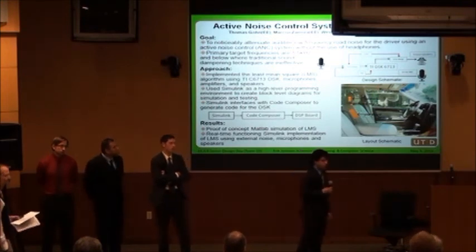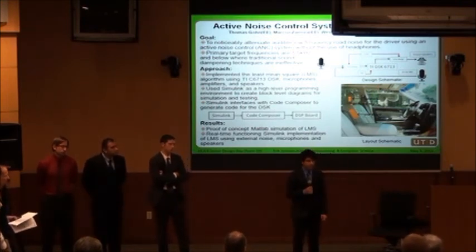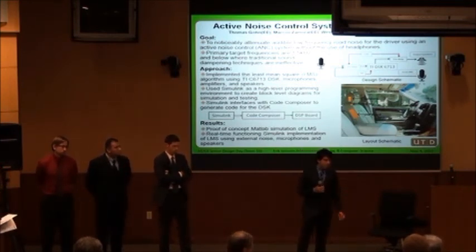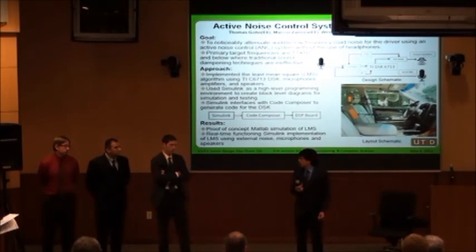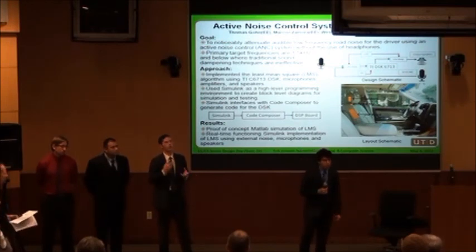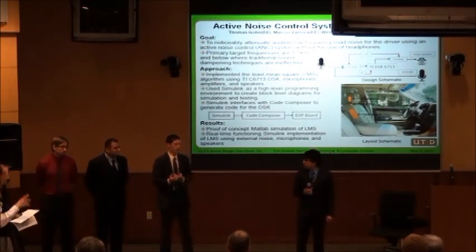One other thing, in your block diagram, you're showing both 12 volt and 5 volt power supplies. Did you implement a DC to DC converter to give you the 5 volts, or did you just hook up to a bench power supply? Ideally, it would work in my car. We had originally planned to run it off of a cigarette lighter, which has power when the battery is on, and we were just using an adapter to have 12 volts for the amplifiers and 5 volts for the board.